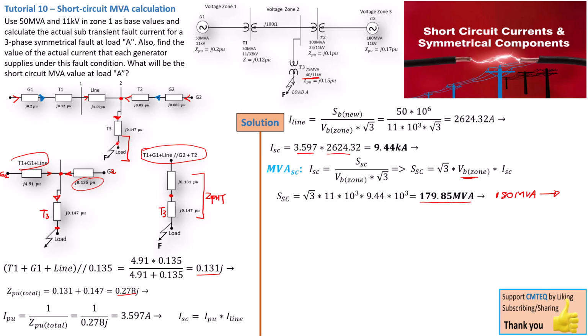Now remember, here is 11 kV. It's at the secondary of the load transformer. And here it's also 11 kV, but this is on the output of the generator. But because this short circuit current is going through an impedance circuit, the current is being dampened, being reduced. That is why we have this impedance diagram, so that we can know exactly what the level of the short circuit current is.